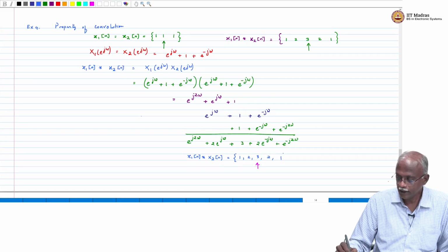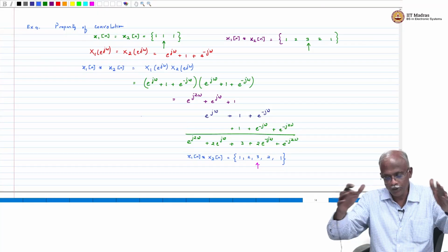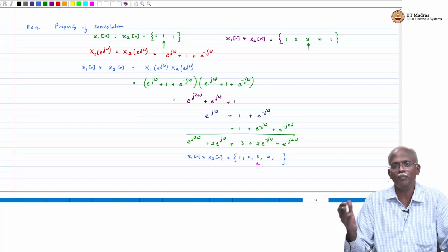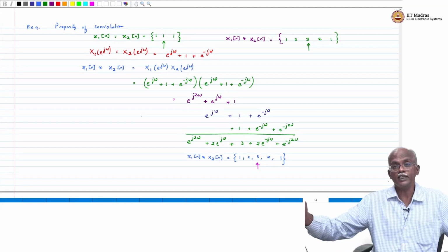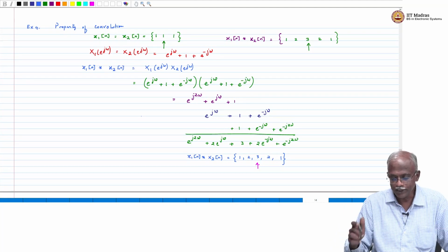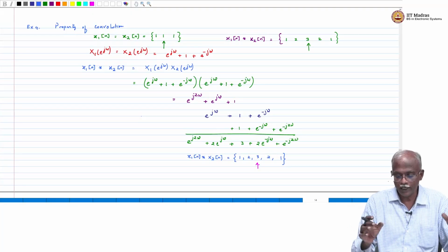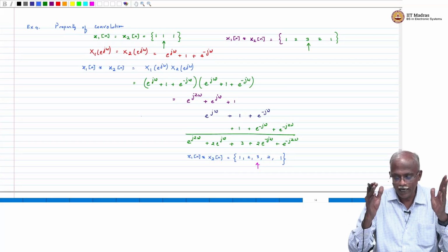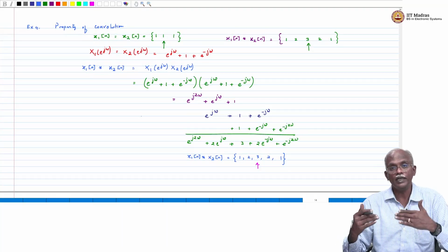Now, this is a calculation in which computing it numerically versus computing it using the Fourier transform may be of comparable level of complexity. Now, when you have very large sequences and you have to do this computation, you will find that the computation using the discrete-time Fourier transform is very, very simple, because you can write a simple program to do these polynomial multiplications, and polynomial multiplication will give the output in terms of that.